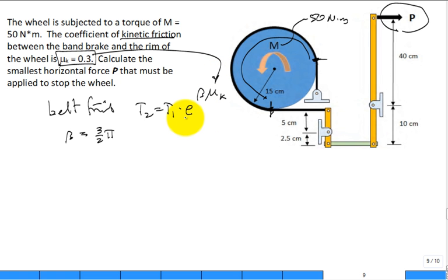Now I have to think about this a little bit. Which one of these segments of the belt has the lower tension or higher tension? We use T1 as our lower tension section of the belt, true? T2 is our higher tension section. So is this T1 up here or T2? I'm using 1 and 2 to be consistent with the book. Your last clicker question for the day. Answer A, if it's our lower tension, T1, in that section of the belt, or B, our higher tension.